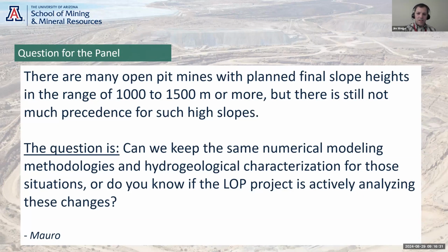We effectively did this for our underground operation here at Kennecott too, where we have the North Lower Chute shaft, and we basically said, hey, we're going to turn it off for a period of time, and we set all our instruments in the area up to a higher frequency of data collection, and we were able to just turn off the pumps and then see how the water moved across structures, and we're able to use that. So we do a lot of large scale tests using our underground workings and our big pumping systems.